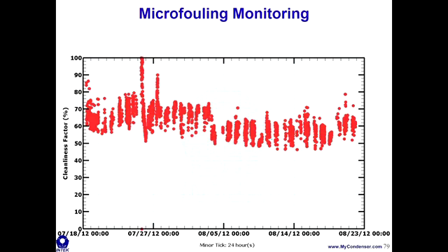But this unit also has single tube flow meters on it. So we don't know at this point if this is due to an air leakage event, a sudden increase in air leakage. We don't know if something happened to the cooling water flow, or if maybe a bunch of debris got through onto the tube sheet. So you can tell the magnitude of the problem, but you can't tell what's causing it.